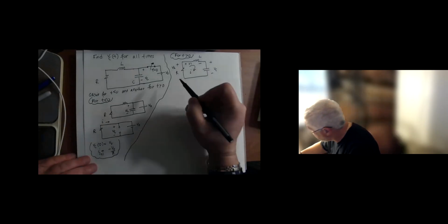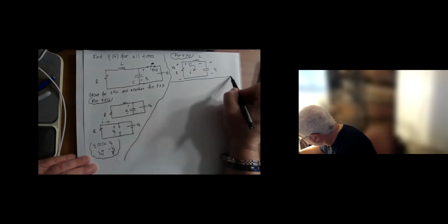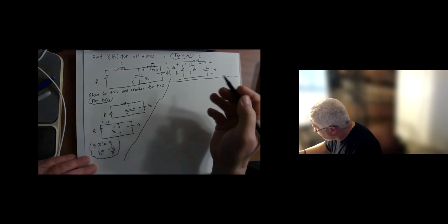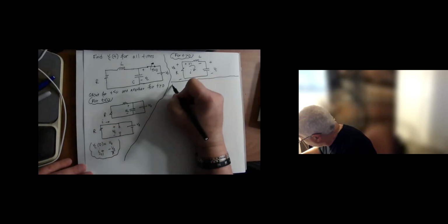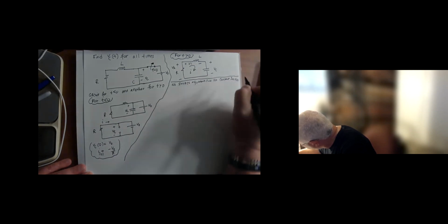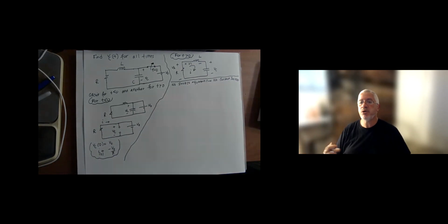So this prepares the circuit for solution. All right, so no source equation, because no current sources. We have source equations when we have current sources in mesh. We don't have any current sources, so no source equation here.